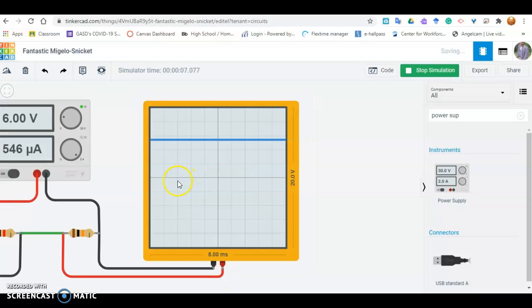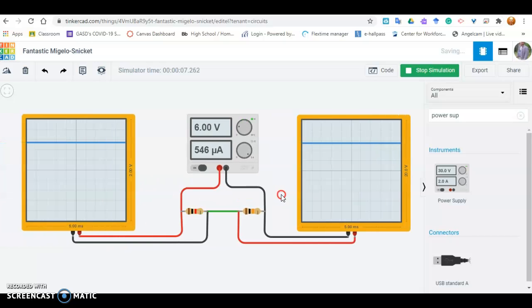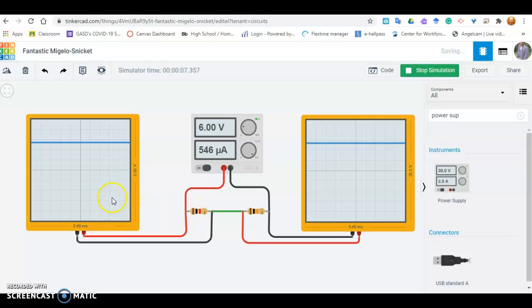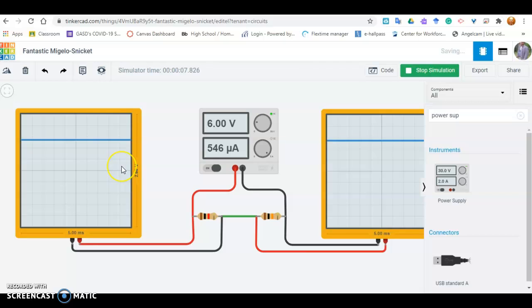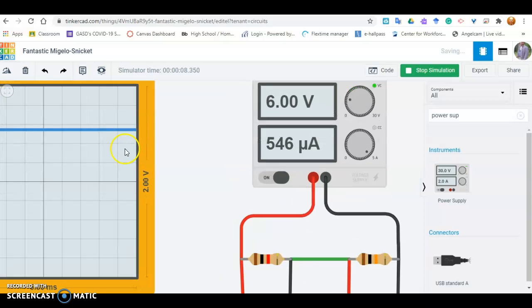That difference matches, so this is my 10 k ohm, that's the significant voltage drop. And 1/10 of that we're seeing over here, and that difference matches. So if that's 2 volts to the division, this one over here is 0.2 volts to the division. Let's look at what that looks like. 0.2 plus 0.2 is 0.4, and we're a little more than half here, so we're 0.5. And we're actually about 0.545 if you calculate it out. And that's what this graph is showing us here.